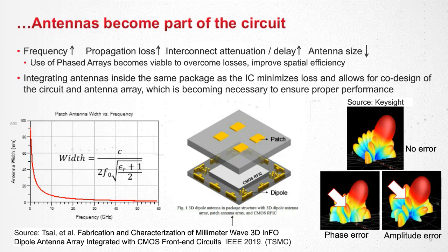So that means it's really critical to be able to design the chip, really the circuits, and the antennas together at the same time. And again, if you go back to 3G or 4G and you think about designing, I've designed a lot of commercial cellular power amplifiers myself. You could design the amplifier and connect it to a 50 ohm load. And of course, you characterize it over some VSWR for an antenna. But you take an antenna and you connect that one antenna to your one part.